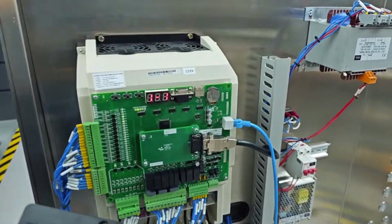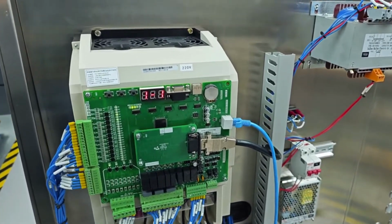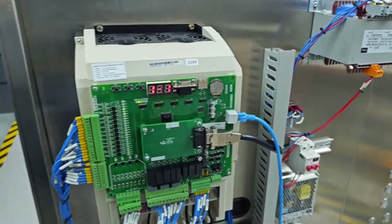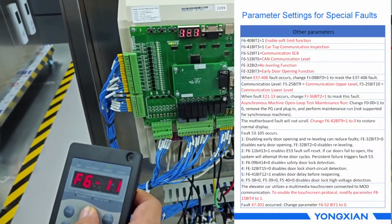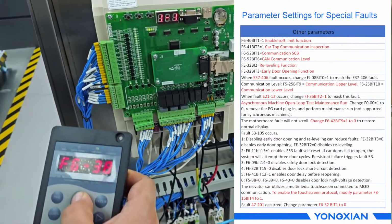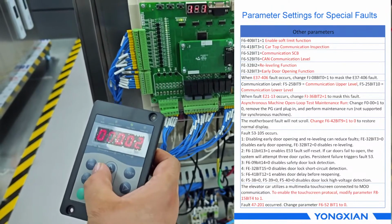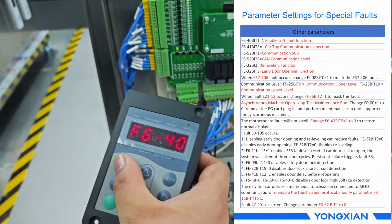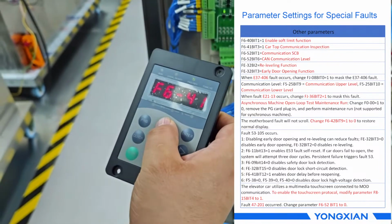我们把它 F0-01设为1，它就关闭了。Set the F001 equals 1, it will close. 然后我们有一个软限位功能在 F6-40里边。We also have the enable soft limit function at the F640 bit 1 equals 1. 将 bit 1设为1。Set the bit 1 to 1. 就是开放我们的一个限位功能。It will open our soft limit function.